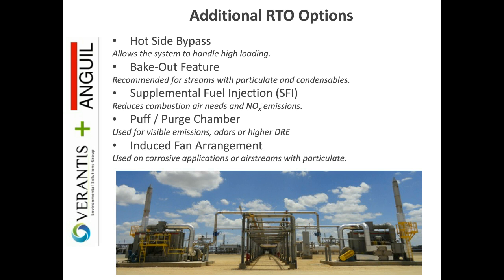The supplemental fuel injection, or SFI. If we do need additional energy input, the schematic I showed had a burner. That's a pretty standard way to get the additional energy we need. A second way of doing that is we can actually shut the burner off completely and inject the natural gas into the process airstream. Really what that does is artificially increase the percent LEL of the process stream using methane as the solvent or the VOC.